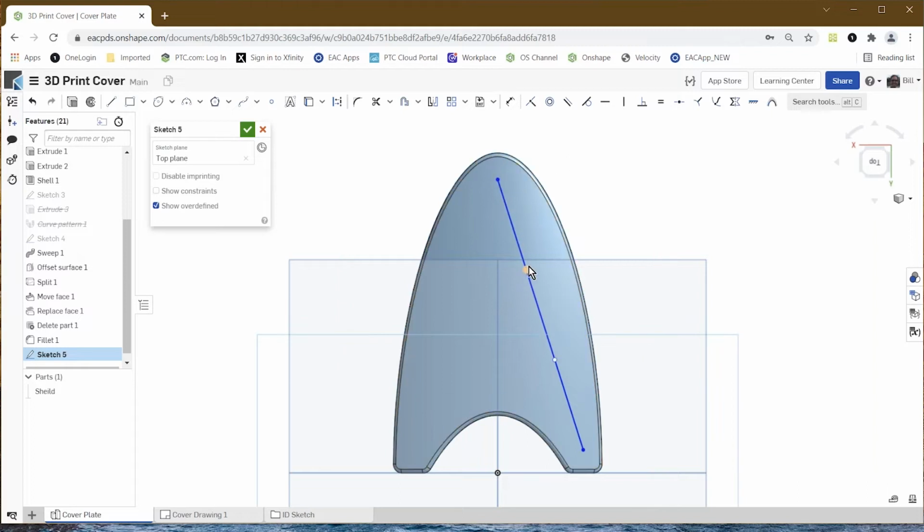And the thing is that Onshape allows us to create a tangency drag arm here that I can manipulate. So it's real geometry. I could take this and say, let's make it horizontal, right? Or I could come in and say, let's put some dimensions on it. I can control the length of this dimensionally. The longer it is, the more pull that it puts on our curve that we have here.